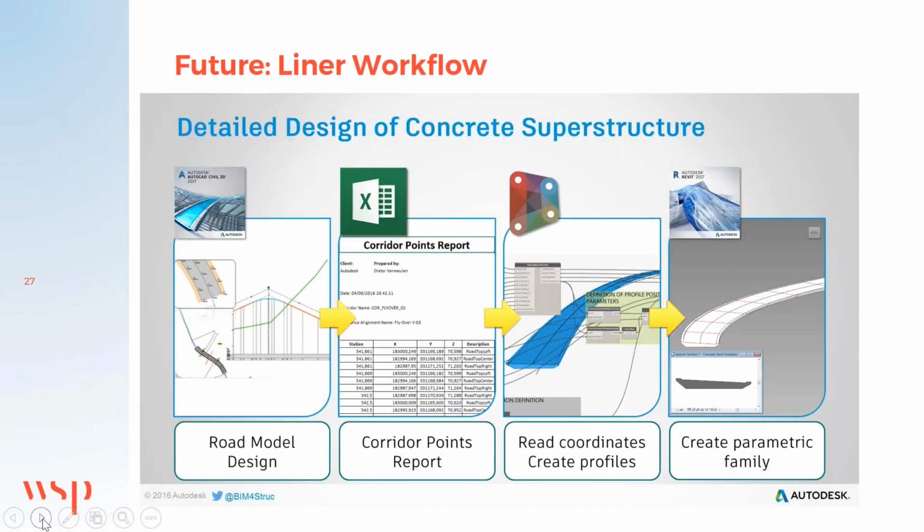However, in the future, we are considering a different approach using Dynamo, in that we can take the road model that is coming from the geometrics team and the pavements team, and if there is a need to make any changes on that model, those changes can be made in Microsoft Excel. From there, these can be exported into Dynamo, and then from Dynamo, we move over to the modeling that could be happening in Revit. This is how we're looking at doing this project and similar projects in the future.